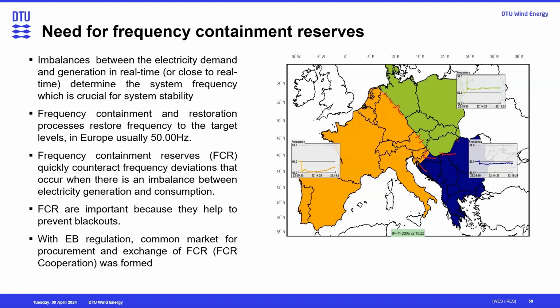In the orange region, quite a lot of load shedding happened. Portugal was doing extensive load shedding because they also had quite some small generators, small wind turbines, in the region, and they did not know how many wind turbines were getting disconnected, so they did much more load shedding than what probably would have been required.